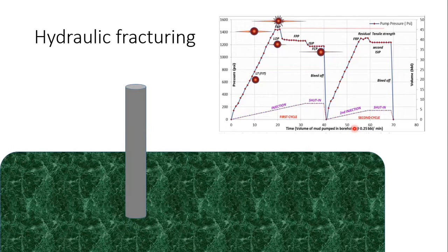So this is an artificial fracture that is going to be generated by injecting fracturing fluids. Fracturing fluid is a technology that depends on the formation, and on how a fracturing fluid has to be designed or synthesized. It could include water, sand, everything which is connected with reservoir fluids. Apart from that, some other chemicals will be added, so that it will start entering into the formation and it will create a fracture. Once the fracture is generated, the fluid will start to move even more smoothly than through the channels which were present earlier. So how can it be observed?